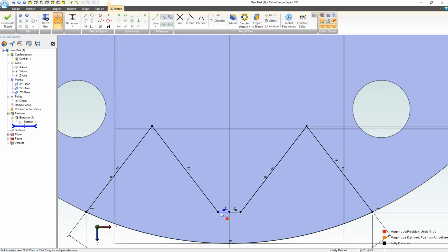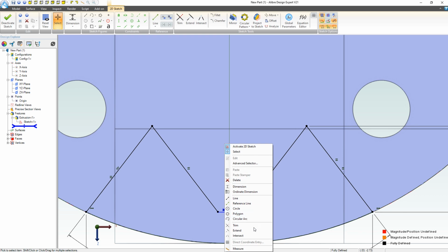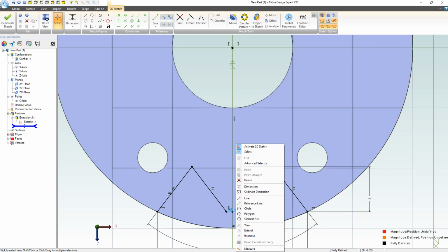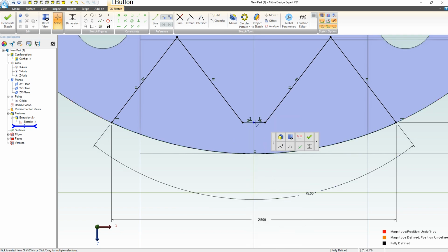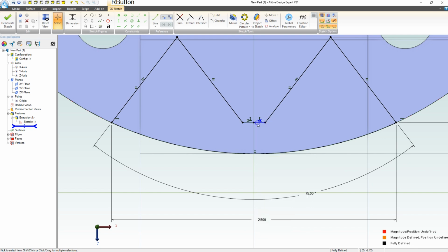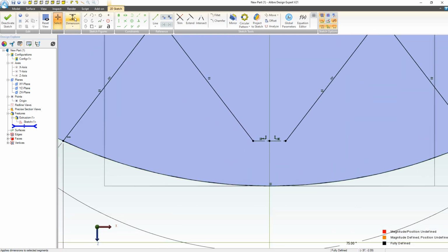So let's Control Z out of that. Here's what I'm going to do. These are keeping us centered, and that's quite important. So maybe if I right click, there it is, convert to reference. That's the ticket. Alright, so those are 2 reference lines now, and what I can do is add a driving line in here, and let's hope that that improves my fillet quality.